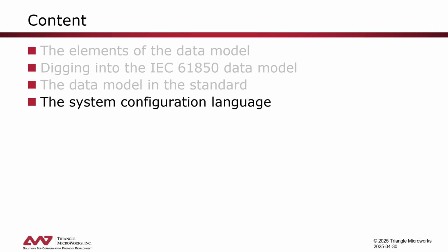We kind of changed the name. It's known as Advanced Client in Test Suite Pro and Test Suite Lite. But no, it is most certainly available. You can browse data models for individual devices, issue controls, subscribe to reports, subscribe to GOOSE messages for that matter. All of that functionality is absolutely available in the currently released version of Test Suite Pro, which can be downloaded from the website today as an eval. Great. Okay, with that, Christoph, I'll go ahead and hand it back to you.